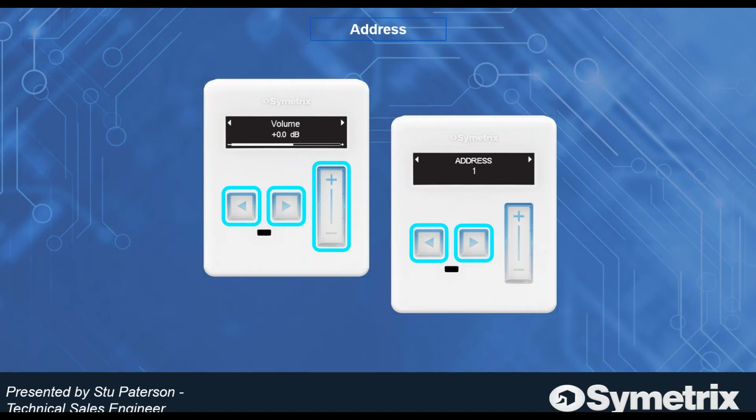The physical address of the ARC3 is set using the system menu. To enter the system menu, you press and hold all 3 buttons for 3 seconds. And then you navigate to the address field using the left or right arrows. If I remember correctly, it's directly to the left or right when you first do it, but you'll find it. There's not that many menu items to scroll through.